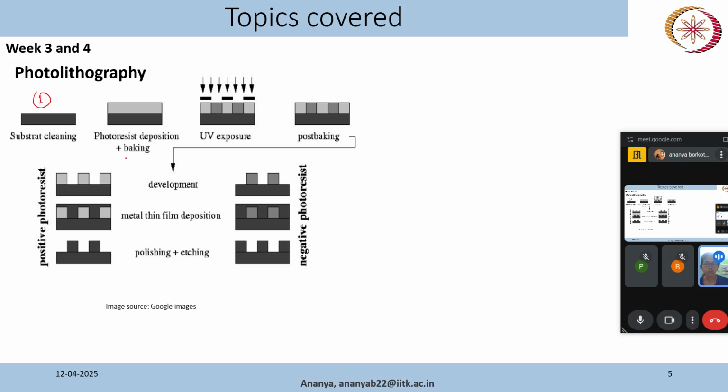What we do next, we go for photoresist coating and soft bake. Okay, there may be another step like primer coating, we have discussed that, to increase the adhesion, but I'm just describing the basic photolithography process. So this is step 2. We will coat photoresist using a spin coater. We know what precautions we have to take during the spin coating, so that there is no air bubble and the layer is uniform. Okay, at the edges the photoresist thickness is uniform, right? We learned all these things.